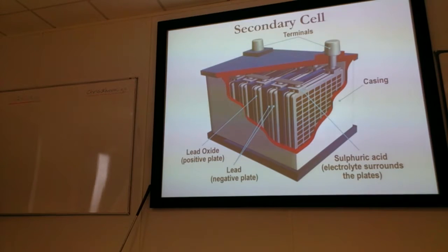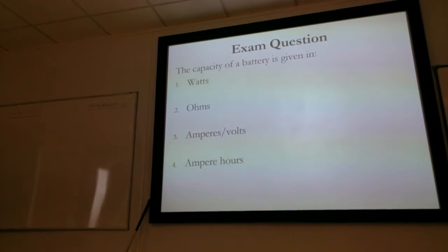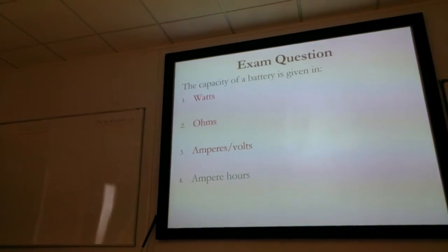If you ever discharge the battery at that rate, you burn it out, you completely destroy it, because there's a thing called a safe rate of charge and safe rate of discharge. You won't be asked about those. But that's the amp hour capacity. So the voltage is the potential difference in it, and the amp hour capacity is how much energy it's storing.